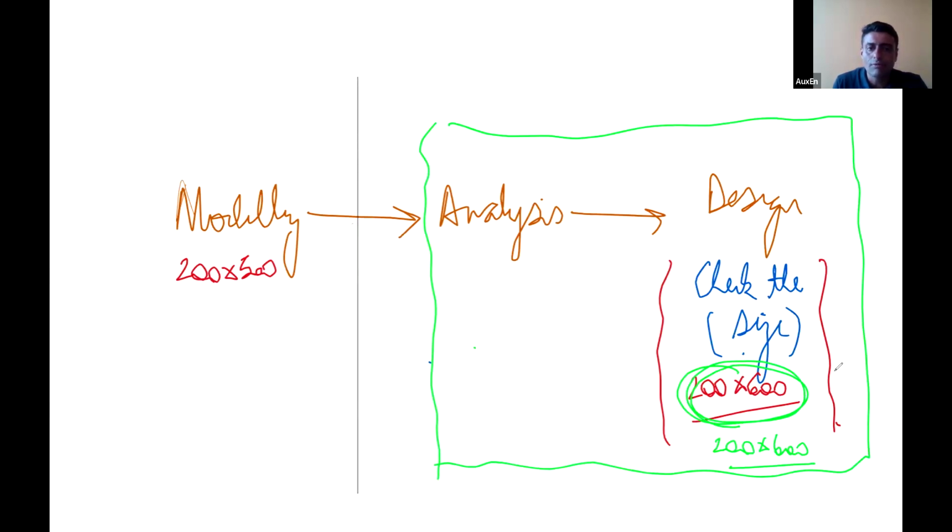This is extremely important for us to understand. No analysis forces will be changed. Why? Because it is unable to perform any analysis on its own, so it cannot change the analysis results. If you change the size to 200 by 600, it will check the new size for the old analysis results. It is unable to update the analysis results. Did you understand this very important point?